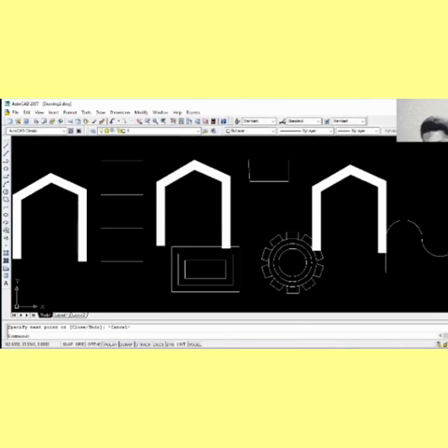Okay, now let me fillet this. I come here, click on this. I click on the first side, then on the second side. Now you specify undo, polyline, radius, trim or multiple. Since you want to choose the radius of the fillet, you click on R and then enter. So now, what is the fillet radius? Let's choose a radius of 1.5. So click this place, enter. You get it? So you can see you've filleted that place.